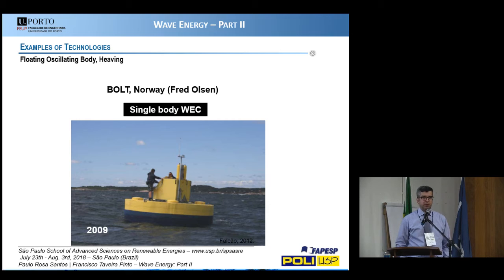And also an important aspect is the maintenance costs, because this type of equipment is exposed to very variable forcings. Since the waves change a lot, the loading on the turbine and all the systems inside the chamber also changes. So you have high operation and maintenance costs, and that is also one of the reasons why the energy produced this way is more expensive than the other way.